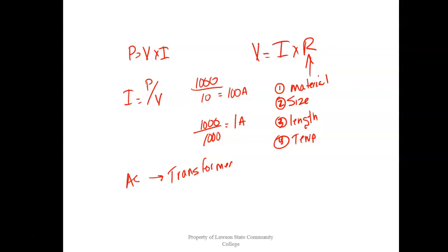Well, what got them is not the aluminum. What got them is when they mixed copper and aluminum. So they'd go out to Lowe's, buy the plugs, and they were copper. And then they'd screw the aluminum into it. These are dissimilar metals, guys. Dissimilar metals will eat each other up. So what would happen, it would oxidize real fast. We're pulling current through resistance, right? It would create heat, and the heat would catch the house on fire.